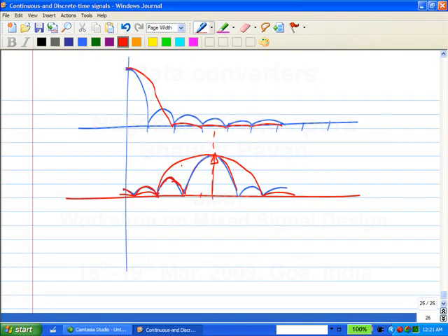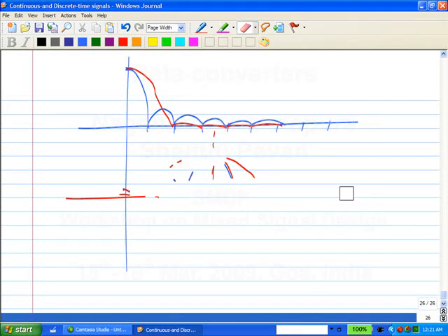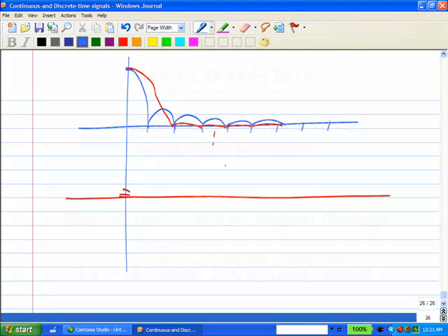Let me now place the sinusoid on one of the good bins for the rectangular window. Okay, let's say the sinusoid was here. Okay, coincident with this. The rectangular window would have given a Fourier transform like this.